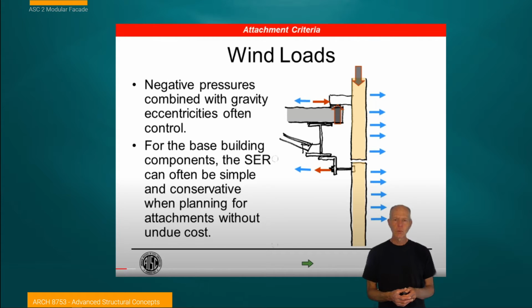It brings up this nuance of what happens at that joint between the two panels. If it is a spandrel and going down like that, where does that panel then join up in relationship to the clip system? If that's a flexible connection, you'll notice the force arrows are going both in the same direction, meaning that that clip can rotate out of position. And then how do we resist that force of it rotating? That's more than we will deal with in the course, or even in our project, but it's the kind of thing that engineers are thinking about.